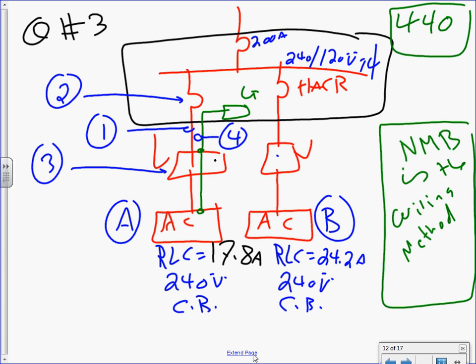And we're going to be using circuit breakers because it says use circuit breaker. Before I go ahead and size, I need to size the following. I need to size the branch circuit conductors. And moving on, guys, here's where I get aggravated. If we graduate from here and you say, I'm sizing the conductors, Chad. Conductors is average Joe talk outside the electrical industry. If you're in the electrical industry, you don't size conductors, you size branch circuit conductors.